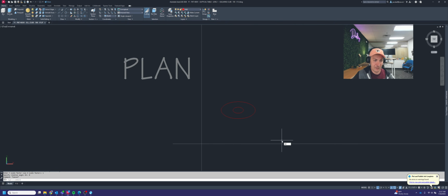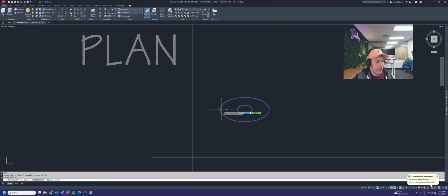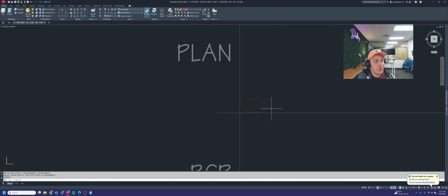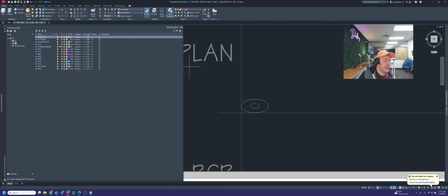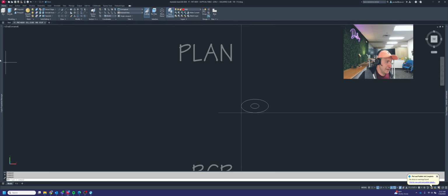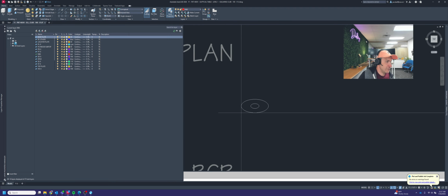So if you want to write those down until you get familiar with that, that is something that you're going to be typing in quite frequently when you're dealing with a 3D model and making flat shots. So after you've made your view, it's a good idea to use the explode command and then set all of your line work to be on the proper layer, or layers, depending on what you're drawing. So I need to go back to my layer properties to get to my 2D lines again. I'm going to switch back to my 2D filters, and I can close out of that.